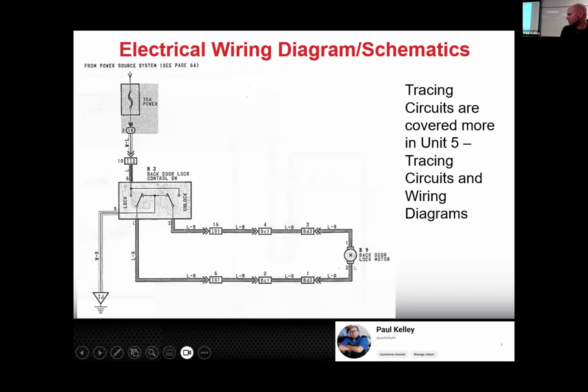And then the next step is where we get in there and put the meter on and interpret a reading. When you interpret that reading, if it's a good reading, great. But if it's a bad reading, your fundamental understanding of electrical will be like, oh, I'm supposed to get 12 volts on terminal 1, but I'm only getting 6. That would tell me there's a voltage drop somewhere in the circuit because you know Kirchhoff's law. And you could even apply Ohm's law: if I've got half the amperage, I must have double the resistance, right? So sometimes we fall back on these electrical theories to be able to actually diagnose this.